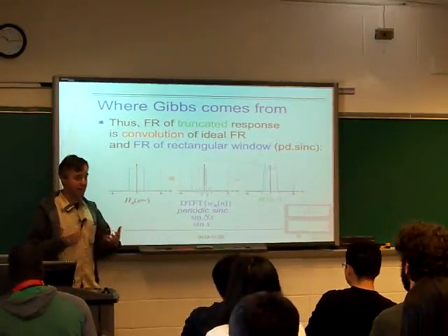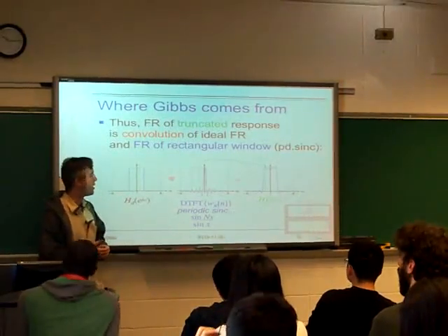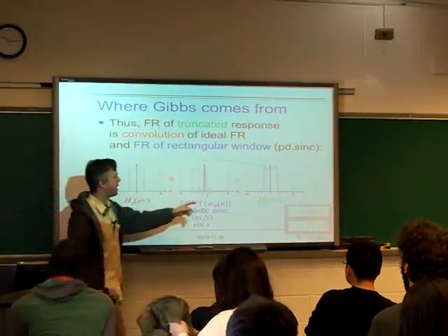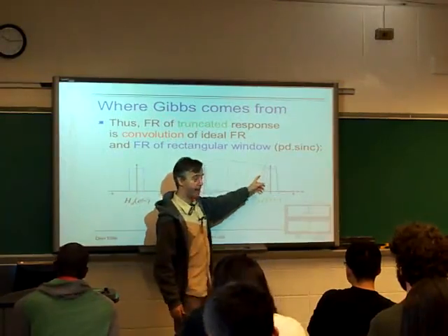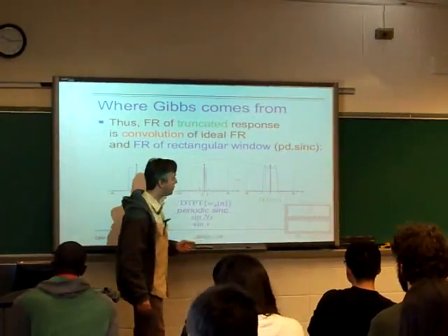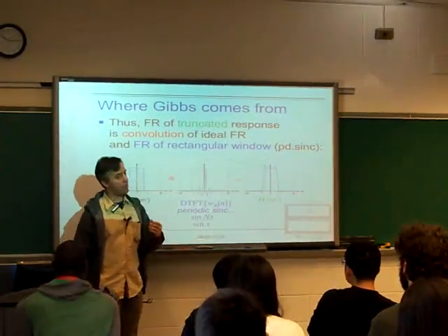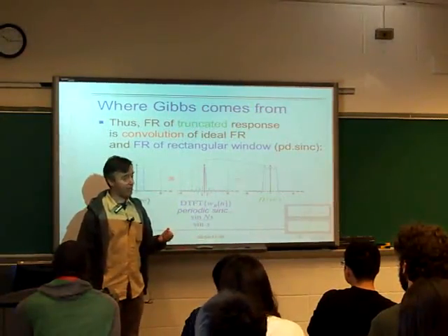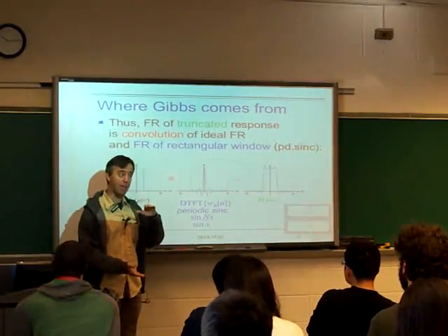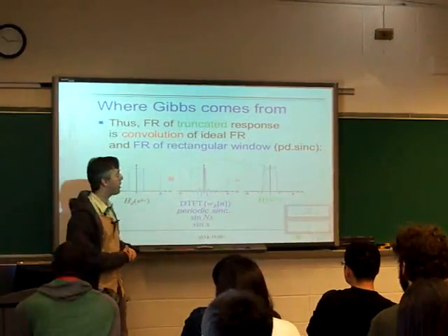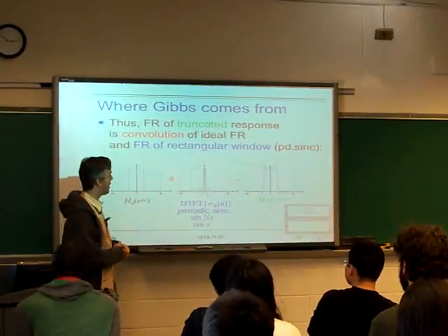That gives us the least squared error approximation, but it gives us filters with weird little ringing artifacts by the transitions, because we were asking for least squared error rather than minimum absolute error, which would give us a different answer.